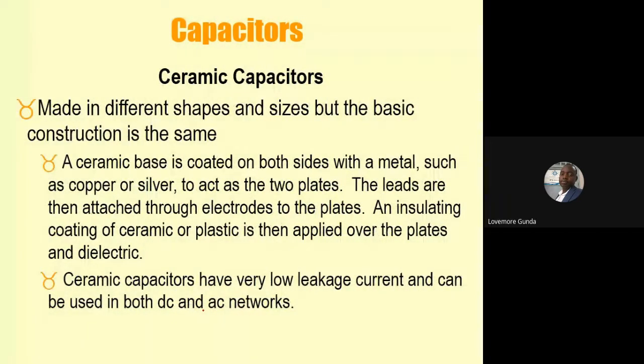Then we also have ceramic materials used also as dielectrics, and they produce the ceramic capacitors. A very low leakage current and can be used in both DC and AC. So these are very common because they are robust. They can also retain their charge for quite long periods of time.